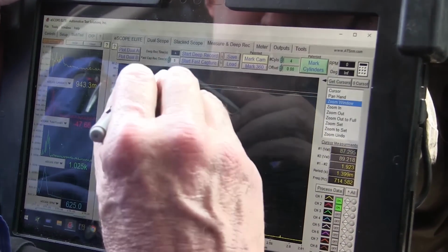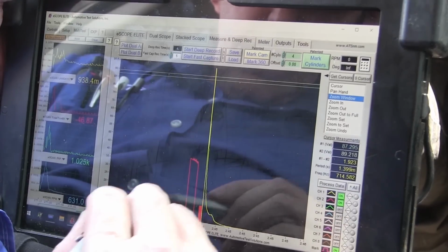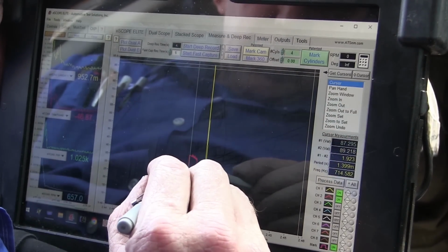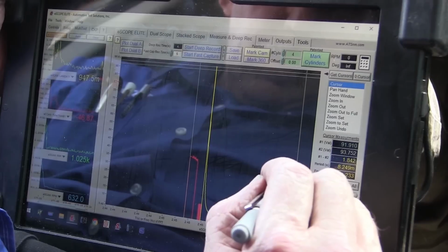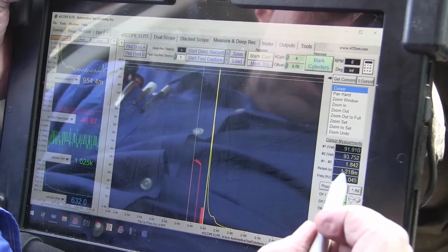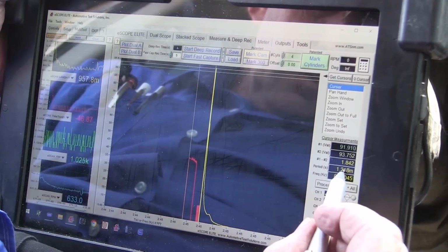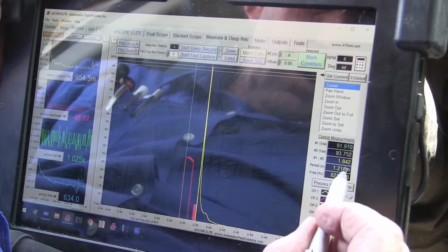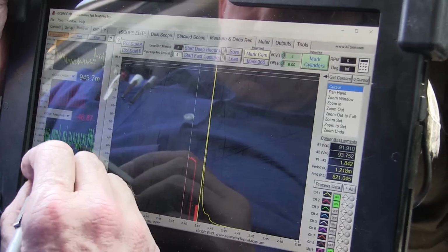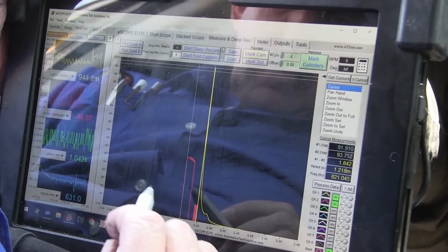Now one thing I want to do to start with real quick is we haven't checked one of these injectors with it just sitting here and I'm in gear. When we were at the shop, all the testing was in neutral. Now we've got a light load on it, so let's do apples to apples. Okay, so I got 121.21 milliseconds, and I've got 500 pounds of rail pressure, and that's right now at idle.